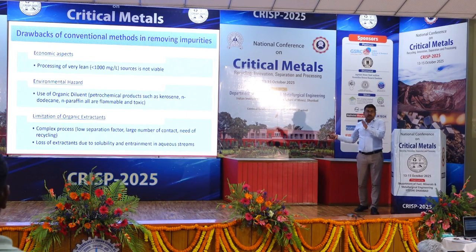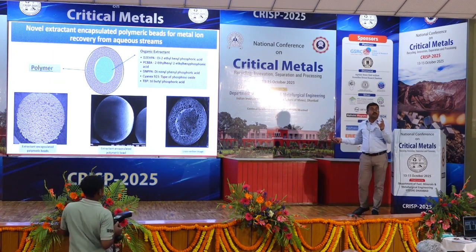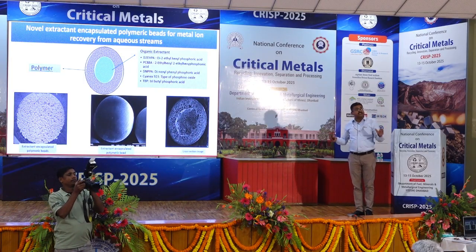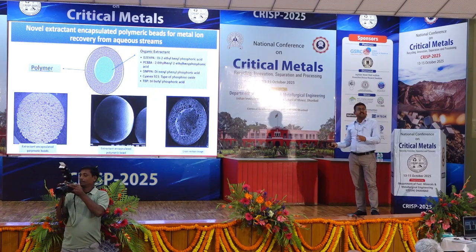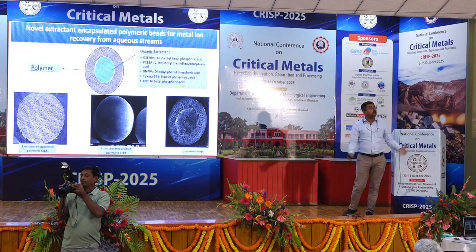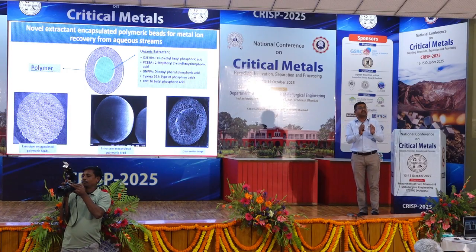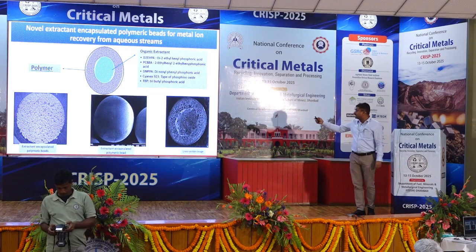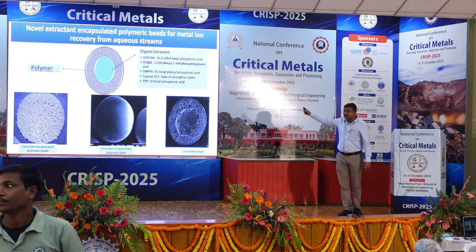So I will not go into the scientific part, but I will just showcase what technology we have developed. So we wanted to develop polymeric composite beads which should have the advantages of solvent extraction and ion exchange. Ion exchange has the advantage of a solid matrix. Solvent extraction has the advantage of bulk extraction. It can extract a lot. So what we have done, we have created a cavity, and inside that central cavity we have fed our organic extractant, and this is a polymeric bead. So the central portion is filled with that organic solvent, and this is porous in nature.